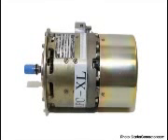The loop of wire A and B of Figure 9:1 is arranged to rotate in a magnetic field. When the plane of the loop of wire is parallel to the magnetic lines of force, the voltage induced in the loop causes a current to flow in the direction indicated by the arrows in Figure 9:1. The voltage induced at this position is maximum, since the wires are cutting the lines of force at right angles and are thus cutting more lines of force per second than in any other position relative to the magnetic field.